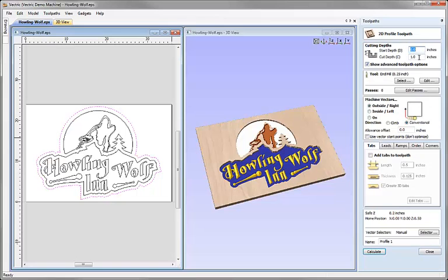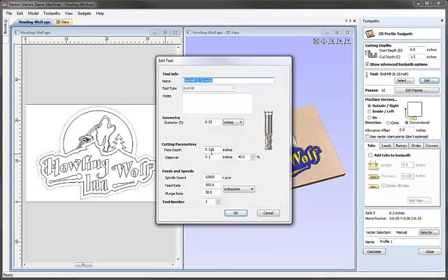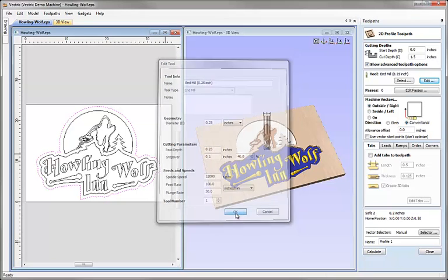Start depth is going to be 0, cut depth is going to be the full depth of the material we've got in here. So I could either type in the value, or I can hit Z on the keyboard and then the equals sign, so that will just pick up that value for me, 1.5 inches. I'm going to use a 1/4 inch end mill so I get a nice detailed cut around the shape of our sign. I'm just going to hit edit on here and change my pass depth to 0.25 for this toolpath. Remember, we're cutting fairly soft material, so that's fine.